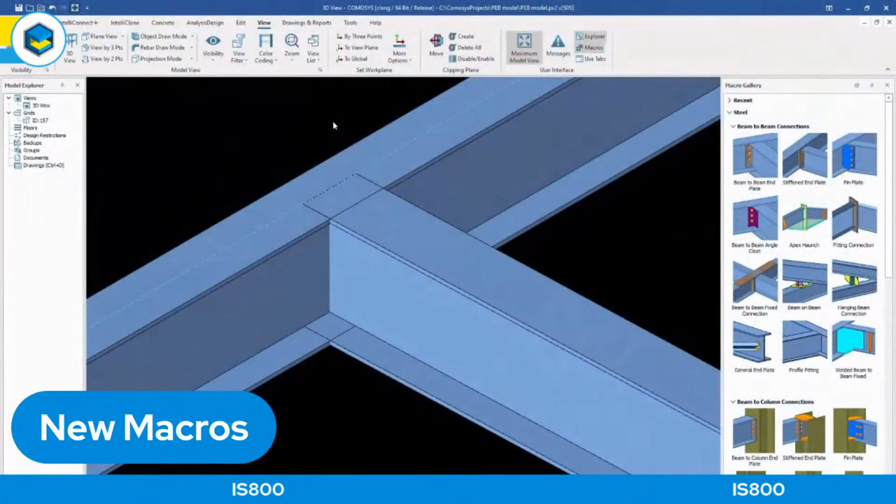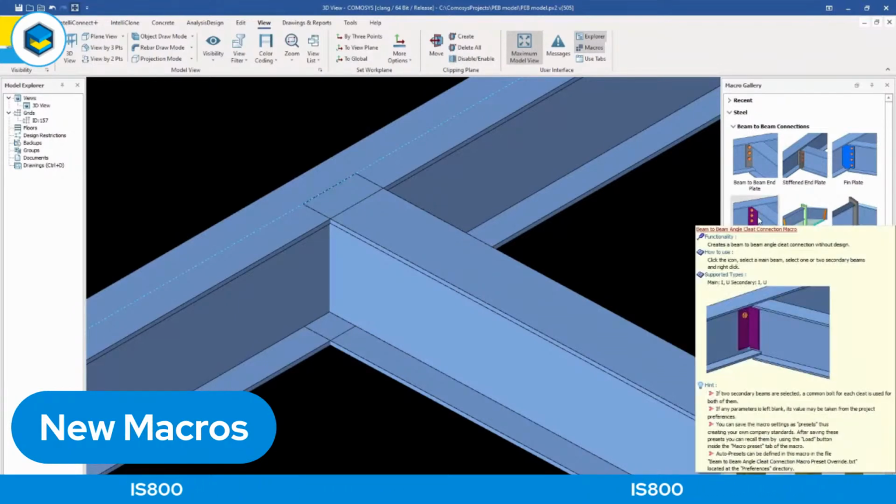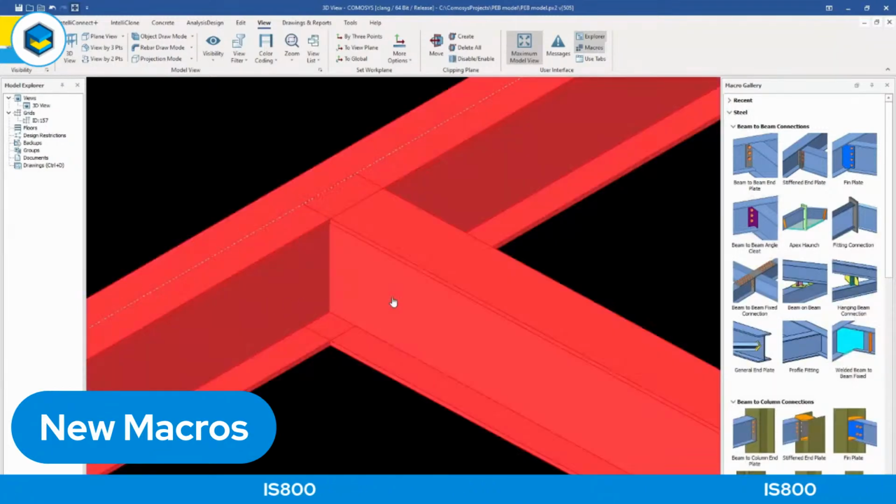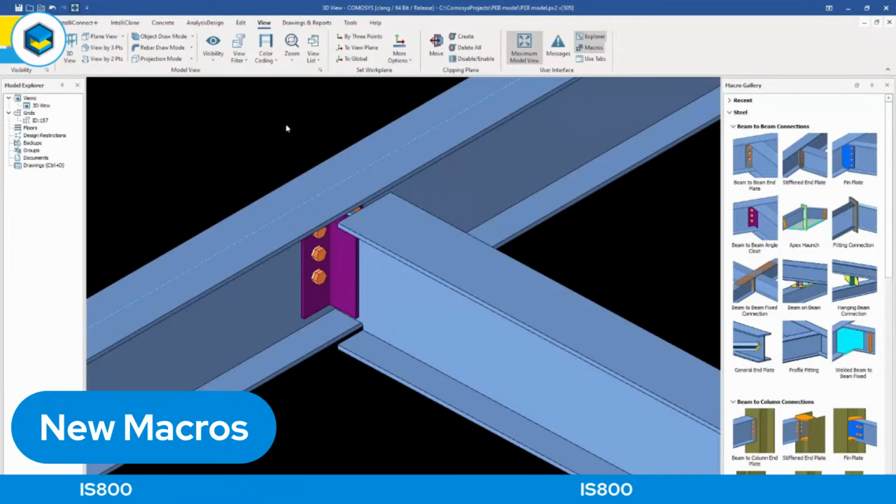Now let's talk about some macro related features which we've added to COMOSYS in this version. The first thing I want to talk about is that we had a lot of requests from our clients that they wanted an extra option in the angle cleat macros. If you remember, the angle cleat macros would connect a beam to a beam with an angle cleat, or a beam to a column with an angle cleat, and the cleat would be welded to the secondary and bolted to the primary. Now our clients requested that we have an extra option of having bolts on both sides.